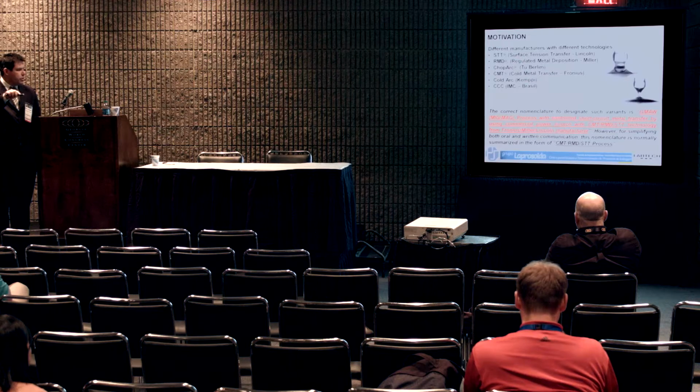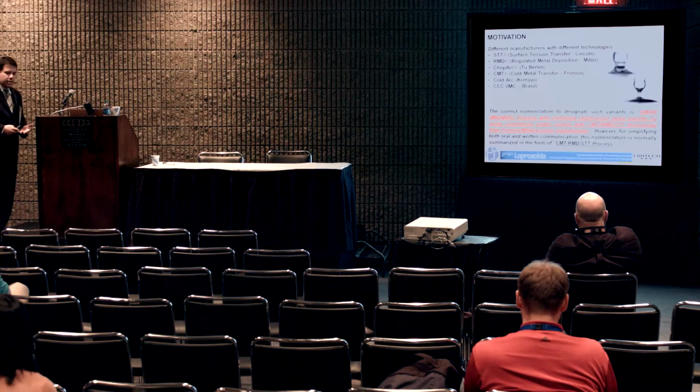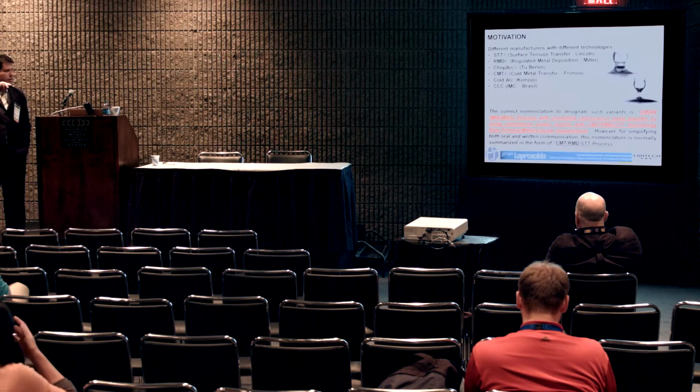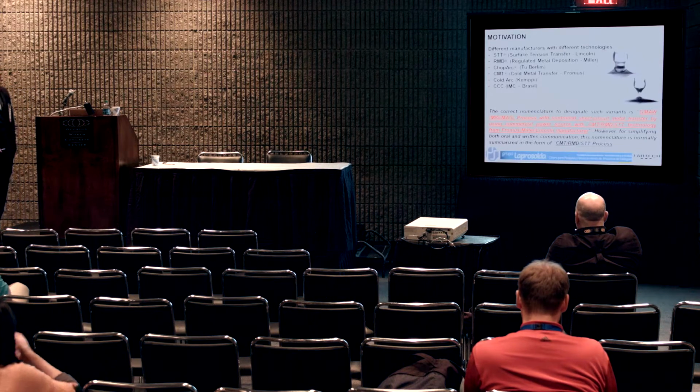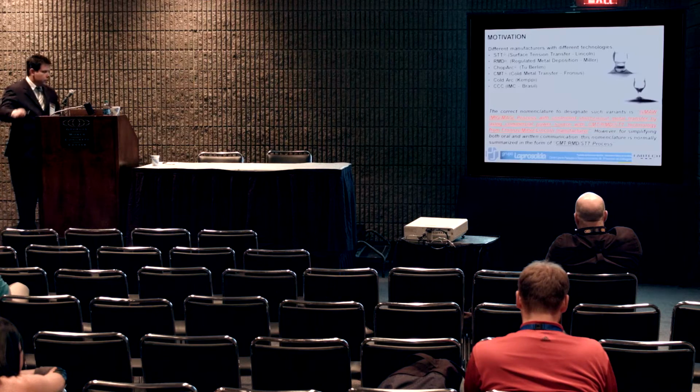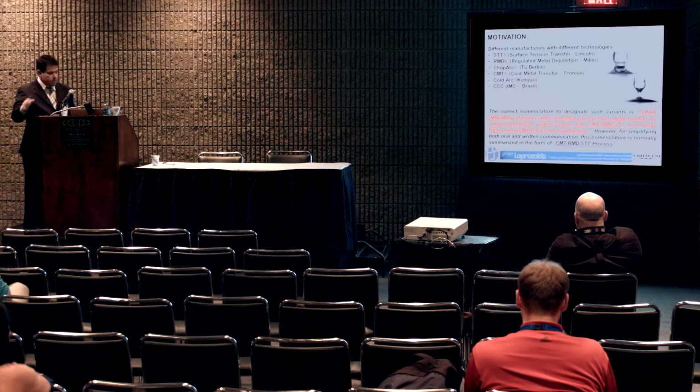So I prefer to call such a set of process a MIG-MAG process with controlled short circuit metal transfer by using a commercial power source. It doesn't matter which manufacturer you select. Sometimes we get lazy and say, okay, it's an STT process, CMT process, RMD process. Indeed, it is not. It is still a gas metal arc welding process, but with a waveform controlled power source. Sometimes we get lazy, but this is just to remind us of a proper way of calling things.